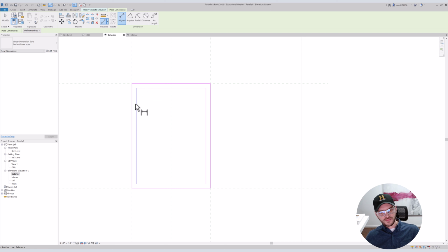And that's right over wherever it is here on the bottom left. Okay, so if you look at the bottom left, you see that information starts to change. If I hit tab, now I can start tabbing through the elements to know what I'm going off of. Because my original line was aligned to the reference plane, I don't want this aligned to the reference plane as well because it's going to create too many. It's just going to put too much stress on your dimensional parameters.